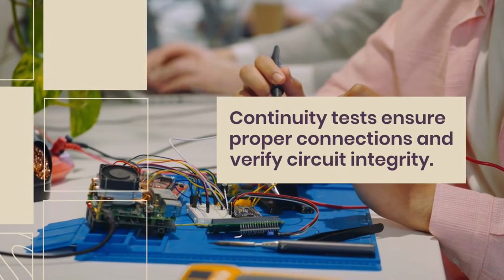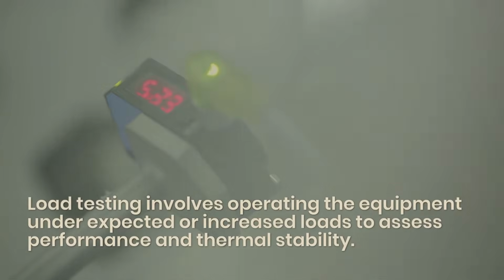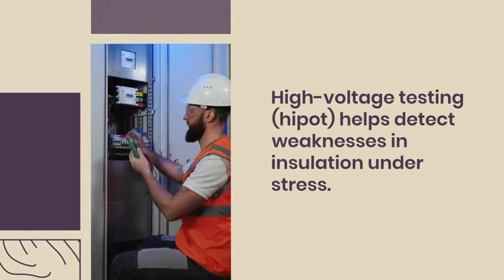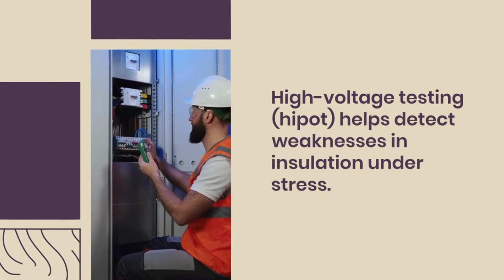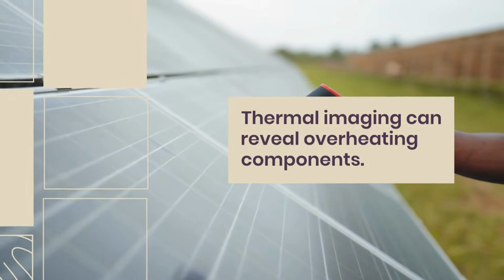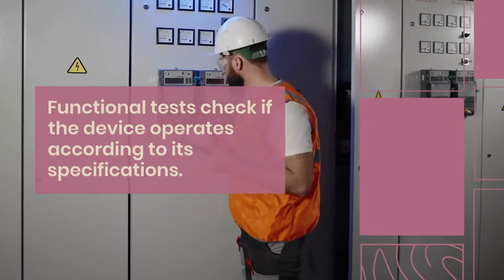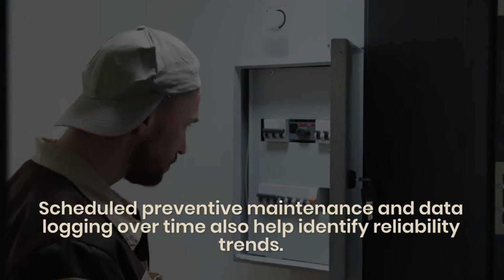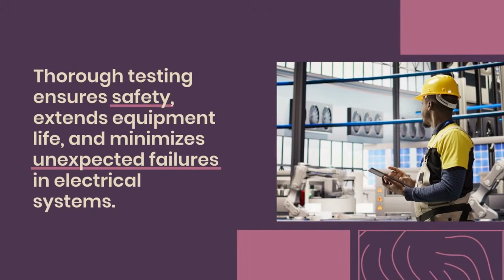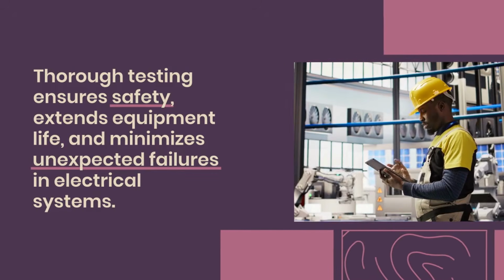Continuity tests ensure proper connections and verify circuit integrity. Load testing involves operating the equipment under expected or increased loads to assess performance and thermal stability. High voltage testing, HIPOT, helps detect weaknesses in insulation under stress. Thermal imaging can reveal overheating components. Functional tests check if the device operates according to its specifications. Scheduled preventive maintenance and data logging over time also help identify reliability trends. Thorough testing ensures safety, extends equipment life, and minimizes unexpected failures in electrical systems.